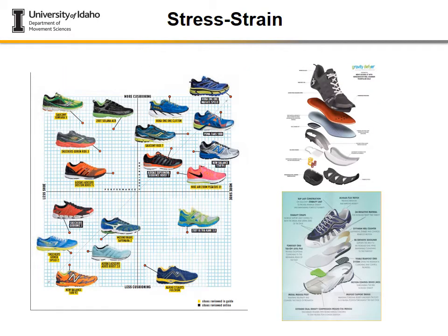One of the great areas where this stress strain curve and impact testing is used is the footwear industry. It's made huge changes and advances with the material properties over the last 4 decades. Materials are selected to give the proper feel. They provide adequate support or lack thereof. They're meant to do great shock absorption or maximize proprioception. Additionally, by doing the material testing, changes in stress strain curve, it has been estimated that shoes need to be changed after a certain quantity of mileage. And you hear that range anywhere from 300 to 500, depending on who you talk to.